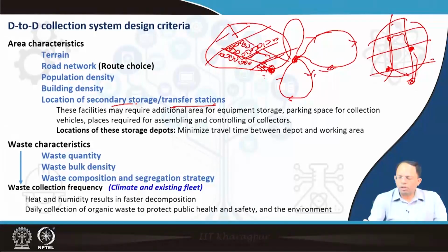So in this case I also have to plan how many vehicles are required, and what sort of time it will take for the vehicle to make this particular trip, and so on. In case of door-to-door collection, the other thing involved is the loading and unloading time, that is, how long a person takes to throw. Suppose a vehicle travels along a particular route, reaches this particular area, and waits there, blows the whistle, and the person may go door to door. There is some time required for loading the garbage or the waste from each generator into the vehicle. So that time will be gone.